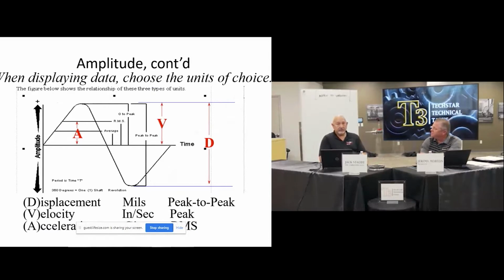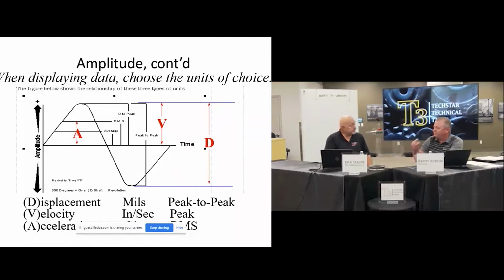And the only difference is the standard that's out, the ISO standard. You just have to remember that your RMS and peak have different distances from the wave. RMS is 0.707 from peak, where peak is 1.414 from RMS. So in your opinion, are you losing any critical data when you go to an RMS measurement versus a true peak measurement? No. No? Okay.